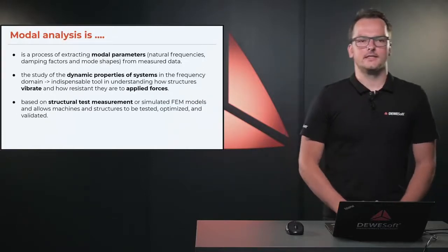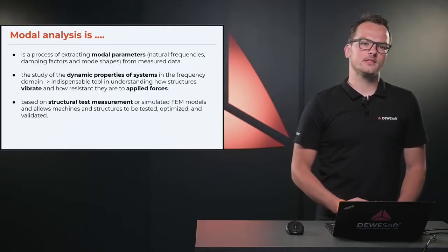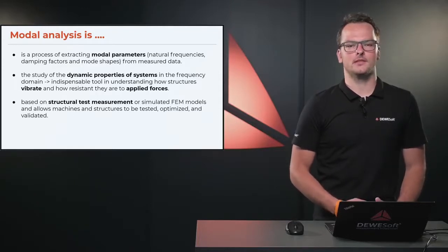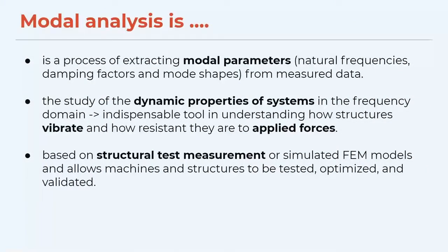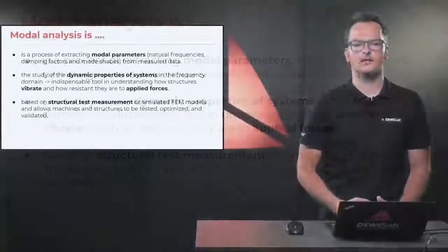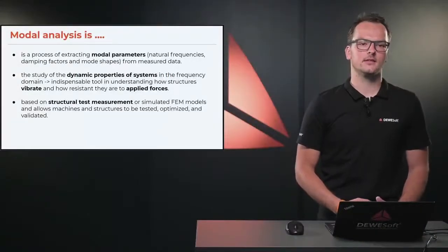So what's modal analysis? Modal analysis is a process of extracting modal parameters. And these modal parameters are natural frequencies, damping factors, and mode shapes. So it's basically a study of dynamic properties of the system in the frequency domain. And it is an indispensable tool in understanding how structures vibrate and how resistant they are to applied forces. It is based on the structural test measurement or simulated finite element models and allows machines and structures to be tested and optimized.